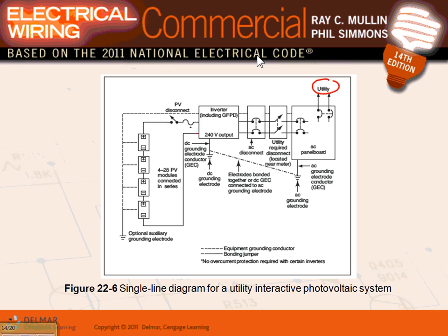Here's my power coming from all these modules, negative, and here's my disconnect for the inverter. Can you guys see my inverter disconnect, my fuse, if any, and I brought them into the inverter. Can you see this is my DC? On the inverter side, I'm inverting at 240 volt. I need a DC disconnect. Here's my disconnect. Can you guys see the disconnect? You have to disconnect the inverter. Disconnect 1, disconnect 2 on both sides of the inverter.